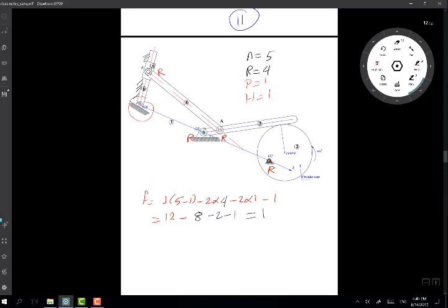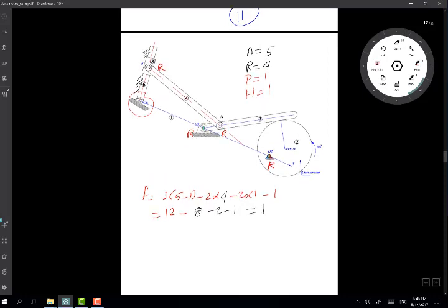Now what this means is the mechanism still functions, still rotates. I still have my motor here attached to the cam and running this linkage. However, when I have managed to fix link number 6, I'm getting a linkage that rotates, meaning that I don't need link number 6 to rotate to be able to operate the linkage. So if link number 6 rotates, that's another freedom in the linkage that I need to control independently with another source of motion or a prime mover.